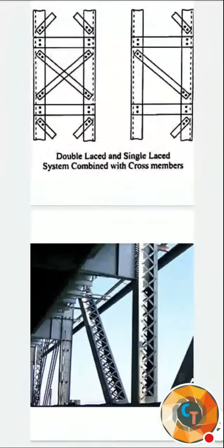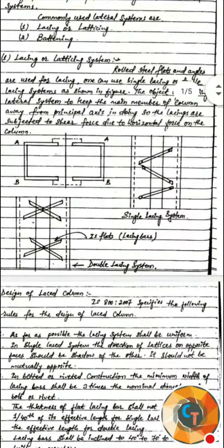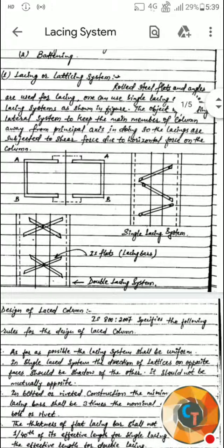Here you need to design, so the section size may be quite high, because it may be around 600 to 700 mm. In that case you need to have columns in such a way that they can carry quite heavy load as compared to I sections, and larger dimensions also. So here we'll be discussing the rules for design of laced columns.